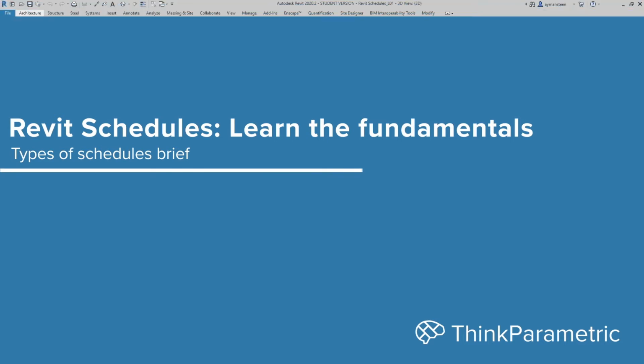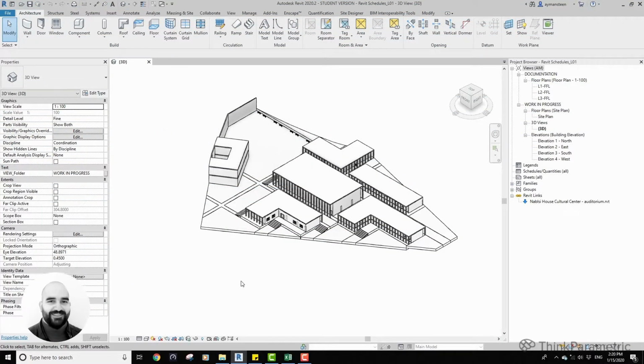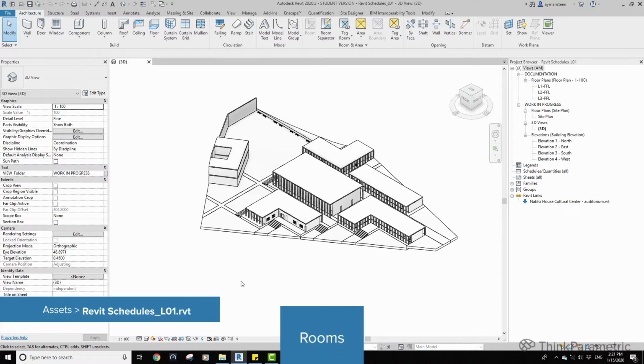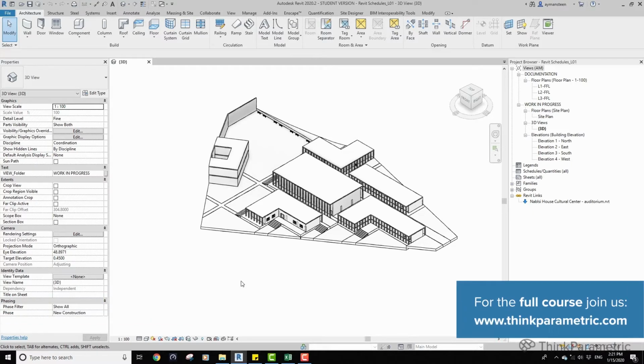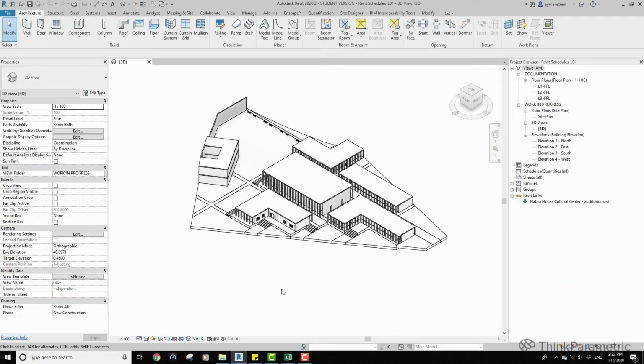In this course, we're going to discuss step by step how to use Revit schedules, how to create them, and how to use the various settings that they have. We'll create walls and rooms, doors and window schedules, and some other material takeoff floors. We'll try to cover most of the important categories inside Revit. We'll also create view lists and sheet lists, and we'll use the example project as a base for the schedules to read the data. We'll start off by creating a simple window schedule.